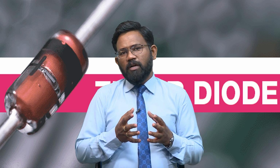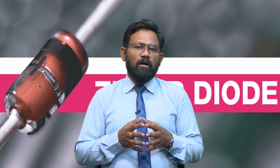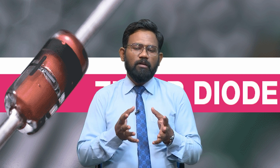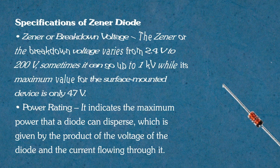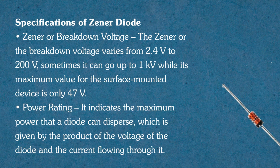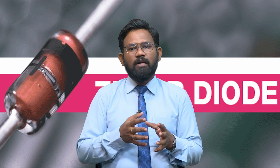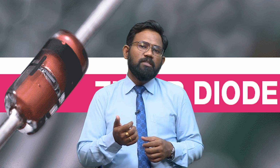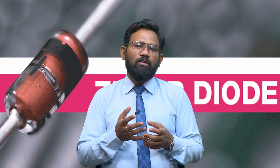These are the particular specifications, or ratings, for the Zener diode which should be known, or which should be displayed with the diode itself. The first one is the Zener or breakdown voltage. The Zener or breakdown voltage varies from 2.4 volts to 200 volts, and sometimes it can go up to 1 kilovolt, while its maximum value for the surface mounted device is only 47 volts. So there are different ranges for different applications. Zener diodes are made with different fixed breakdown voltages, so that is mentioned as the rating.